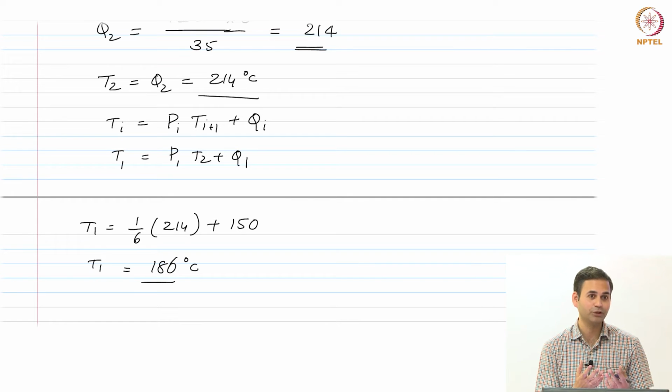Now, all these things we are discussing, you can play with once you write your own codes, for the 1D equation or for the 2D equations. You can start playing with all these things. Other questions? Yes, you can start off with a guess value that is outside the bounds, for example 0 is out of bounds. But your guess value also plays a role in convergence, you may actually diverge as well, that is also possible. So the first solution that you start off with should also be a good guess.